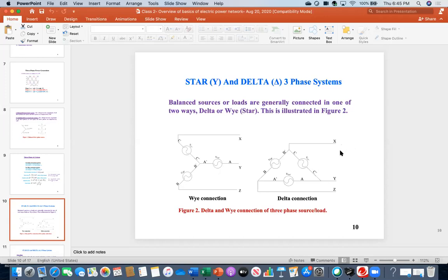Yes. So therefore, Manoj, you remember you were telling about that inductor. There are some arrangements to prevent such a situation. If you put an inductor here, that inductor will absorb some of those additional currents, and that will work as a filter.